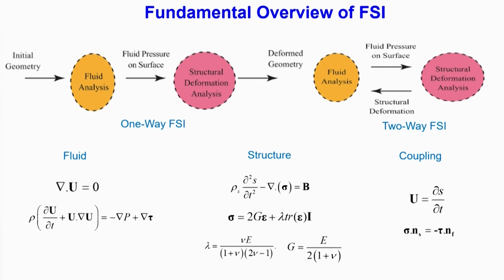For a Newtonian fluid, you have a similar first term and second term. The first term is related to shear strain rate, or maybe also linear strain rate, and the second term to volumetric strain rate. So, you see a lot of similarity in the mathematical form. Loosely, if you just keep in mind that for a solid I care about displacement and for a fluid I care about velocity, you have got the essential feel of what you are working with.